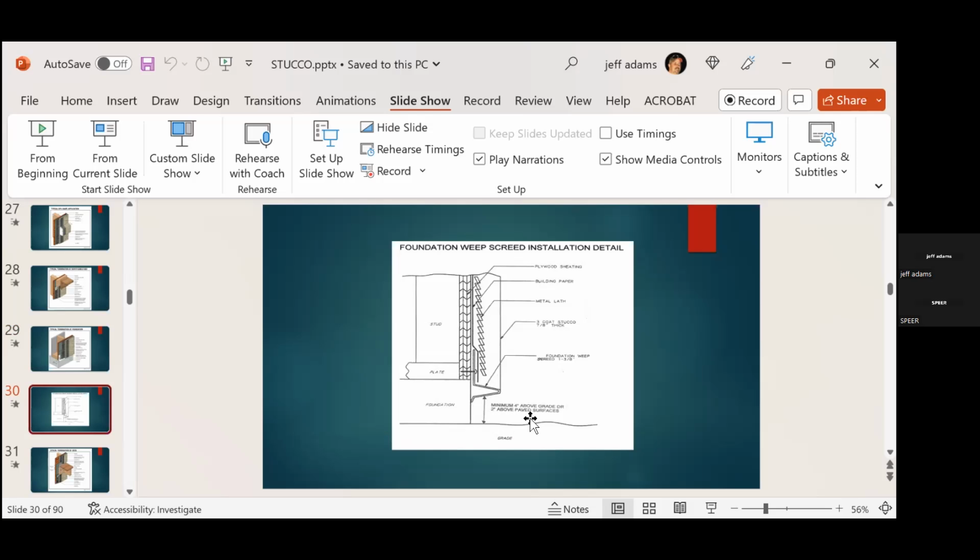It gives you your 2-inch clearance to the ground. If you don't get those 2-inch clearances, you're going to pull water up into this plaster. It's going to wick the moisture up in there. It's a huge issue that occurs, especially when we have stucco columns. Stucco columns, masonry columns are all failing everywhere because they are actually not lifted up. They're just bringing this pressure treated wood down, and they're bringing the stucco right down to the bottom of it.